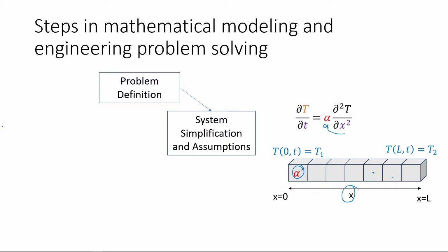So if that is a relevant assumption, I could assume 1D heat conduction, which is called heat conduction along the length of the rod, like one-dimensional heat transfer. So I could ignore, for example, radial or circumferential direction. Okay.